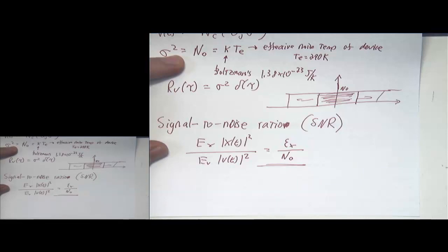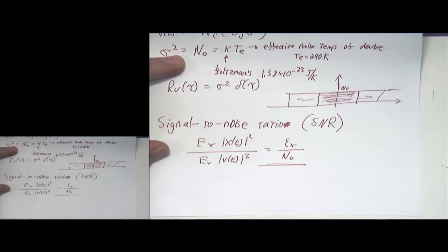If you make 1 symbol error out of every 5 symbols, is that good enough or not? Or 1 out of every 100 symbols? What is the target error rate that your system can support? Because you're going to have coding on top of that. It's really the coding that lets us fix all of these errors. And even with coding, you're still going to make errors. So the whole system is designed not to be error-free, but to work with errors.